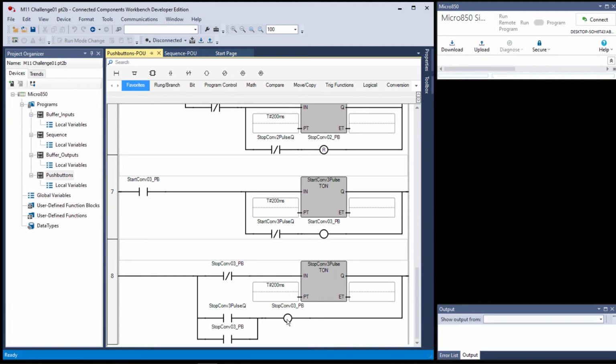If it's already off and you swipe your hand down, that's the motion to turn it off, but it was already off, so you might think that's a wasted motion. That's just how these instructions work, because to do it any other way would be a waste of processing time. So you just have to keep in mind, this is scan sensitive. It makes a difference what order this logic is scanned in. If you flip this all around, it wouldn't work. This rung would not work if you flip the logic around.